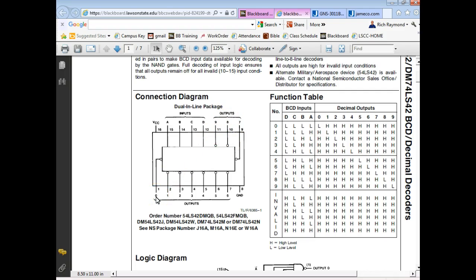Now this gets people confused, because we have the name of the pin and then we have the pin number. The name of the pin is out here on the outside. So the name of this pin is 0. The pin number is what? 1. Y'all understand the difference? This gives us a little problem a lot of times where the name of the pin is a number. So this right here, pin 7, is named what? 6. Yeah, it looks like a 5 to me, but yeah, 6.